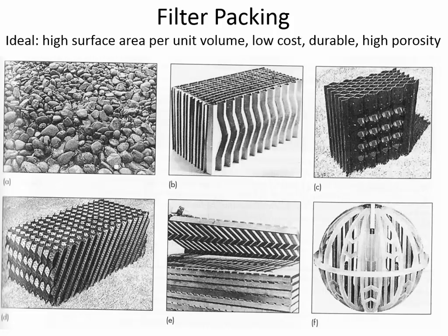You want to maximize the surface area, but there's a limit, because if the slime layer itself is getting up to 10 millimeters thick, then you can't have a really, really small structure for it to grow on, or else the slime layer is going to intercept itself between the layers of the sandwich board here, for example. There has to be something for the bacteria to adhere to. It can't be too slippery of a surface.